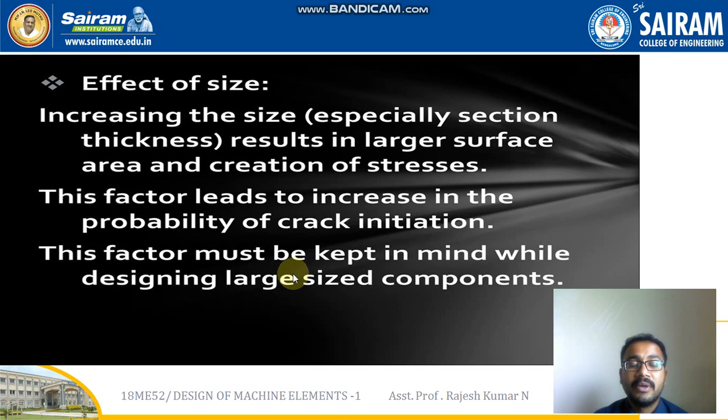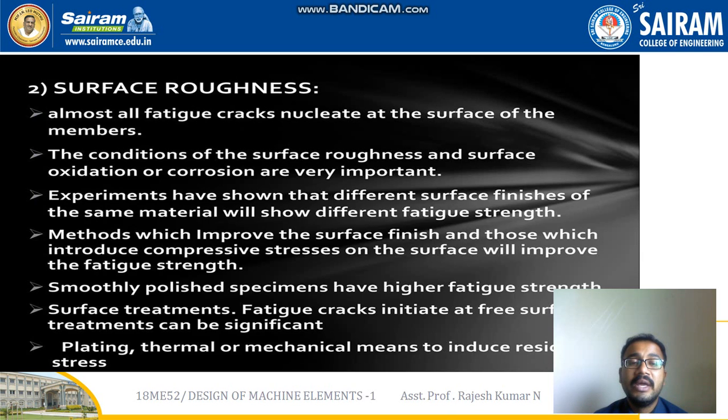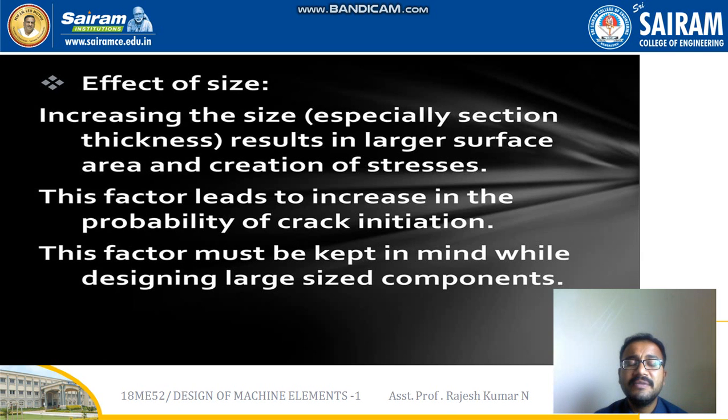Increasing the size, especially section thickness I am talking about, results in larger surface area and creation of stresses. These factors lead to an increase in the probability of crack initiation. This factor must be kept in mind while designing large size components. For example, when I speak of the size factor, it is based on the diameter only, because for a fatigue component the well-known example is the shaft, and it is always considered based on the shaft only.